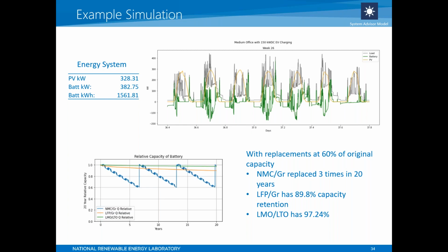And then in yellow, we have the PV production. And then in green, we have the optimal battery dispatch that was optimized against a specific utility rate in order to reduce the electricity bill. So what we can see from this battery dispatch profile is that there are many small cycles throughout the day. And in general, the battery is quite heavily used, like 6 out of 7 days this week. And in the entire year, about 120 full energy cycles have elapsed.